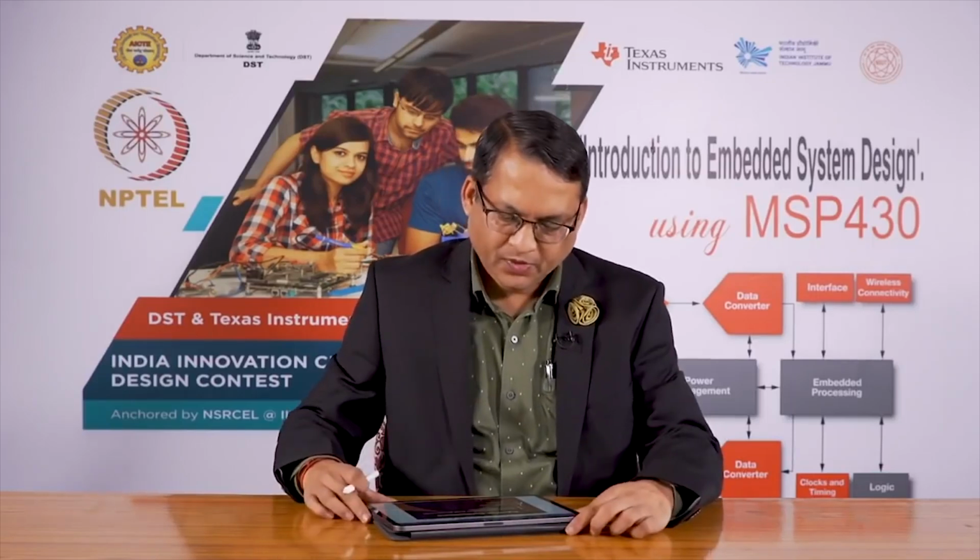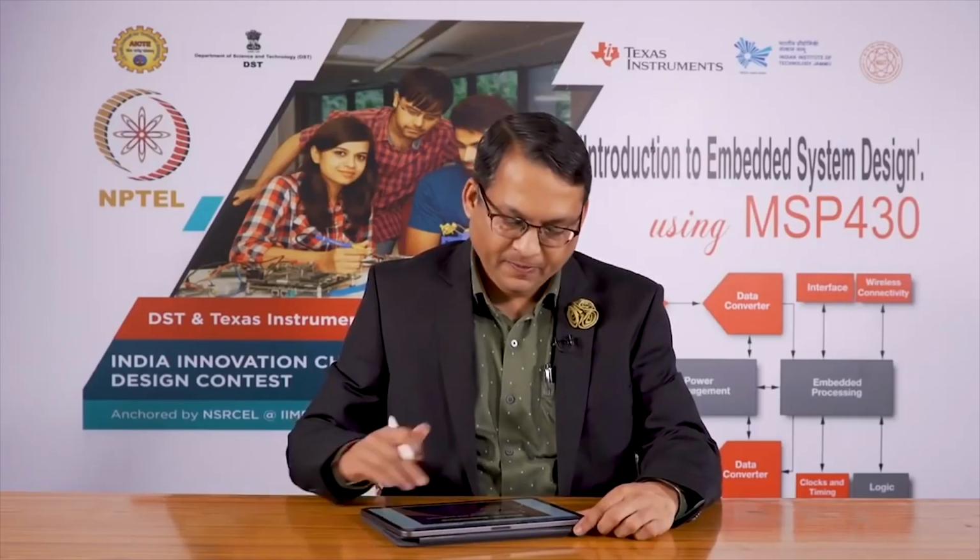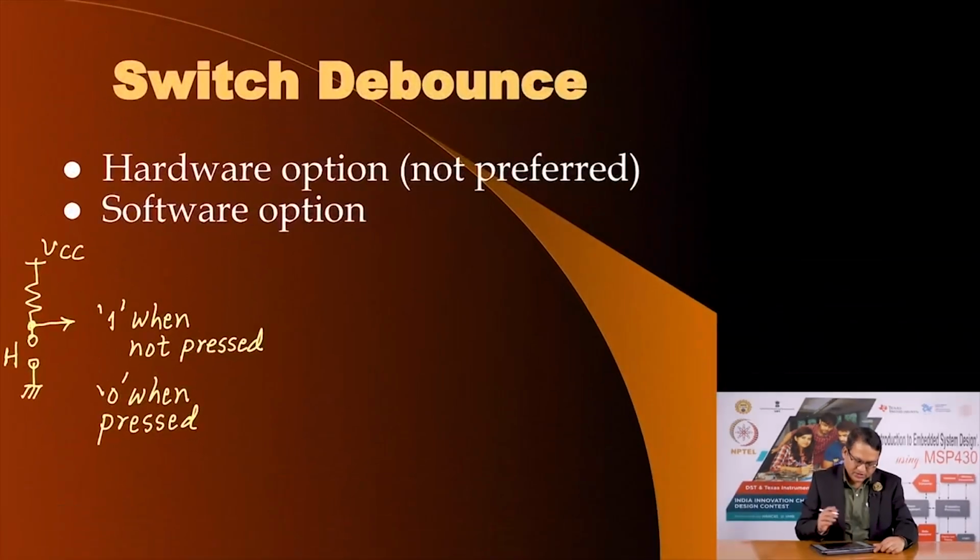Hello and welcome back to this session. In the previous session we had seen how we can connect a single switch to a microcontroller pin, and just to reiterate and also talk about the debounce activity using software. If the switch is as you see in this slide, if the switch is not pressed then it will give a logic 1. When the switch is pressed it will give logic 0, but when you press the switch it will bounce, and how to handle that in software is what I am going to write here again.